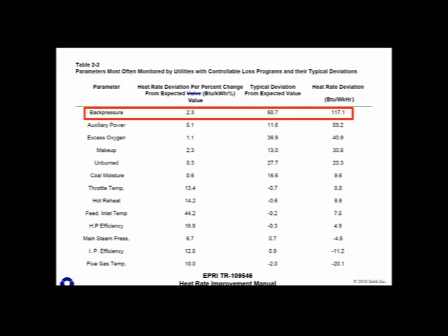So in summary, and I think that's a very typical case, a lot of plants get themselves into a pickle because of not monitoring or not having a continuous effort to address air in-leakage or address fouling, and then when that event does happen, it causes real problems. And so again, in summary, giving a high priority to keeping the condenser pressure low is addressing both generation efficiency and generation reliability. That's the way I look at it.